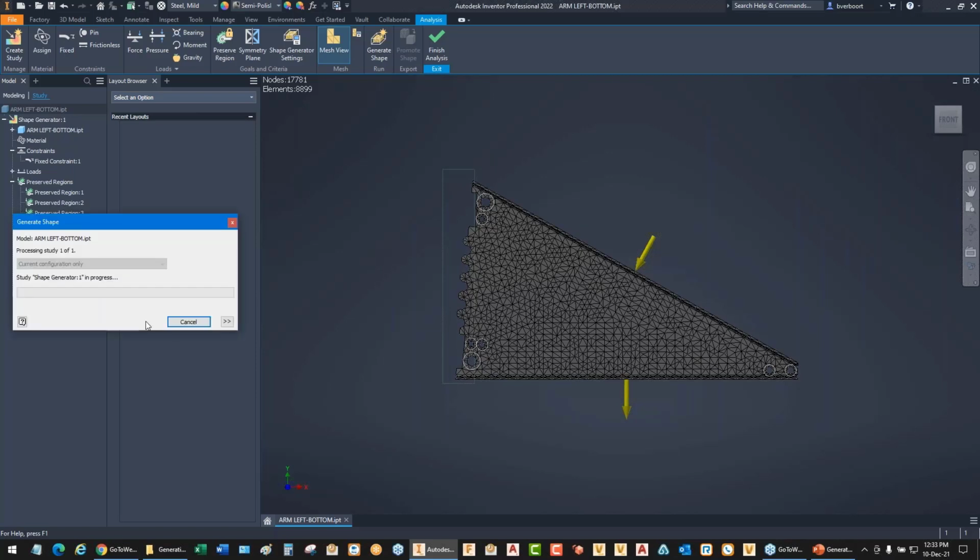Now notice that there's a dialog box that comes up. It'll actually check your work if there are any deficiencies in the setup that you've done. You don't have a load where you should have a load, or a load's completely missing, or there are issues with the mesh size that we chose manually, whether it's within the boundaries or outside the boundaries of what is allowable.